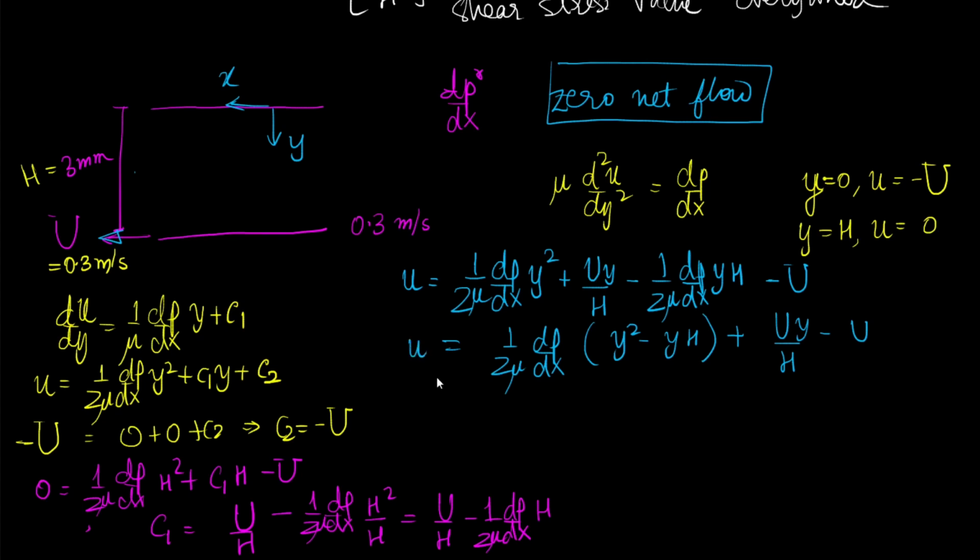So now we can integrate this over the entire channel. So this is not the coordinate system; we have used this coordinate system only. So Q is equal to integral u dA. If we assume the width into the paper as W, it will be u W dy. If we assume a unit width, this W can be simply removed. So remember that these calculations are all per unit width. So this integration will be from 0 to h.